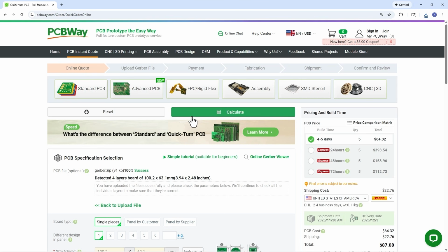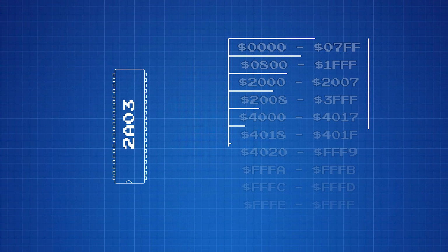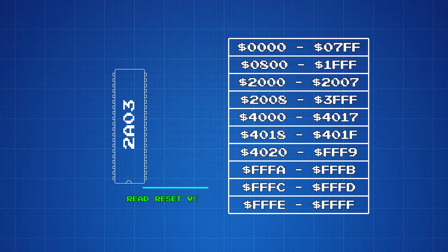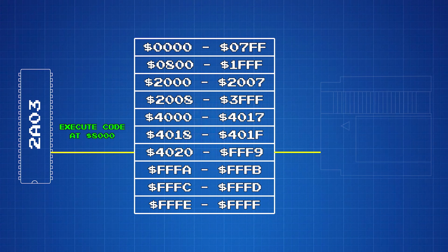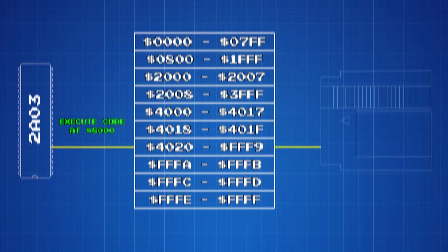Alright, before we can jump in and start looking at the architecture of the flash carts themselves, we need to go over some of the fundamentals around how game cartridges work. Every game console has a central processor or CPU. When you power the system on, the CPU immediately starts fetching instructions from a known memory address. In a cartridge-based system, that address maps directly to the cartridge connector. So the CPU literally begins executing code straight off the game cartridge.